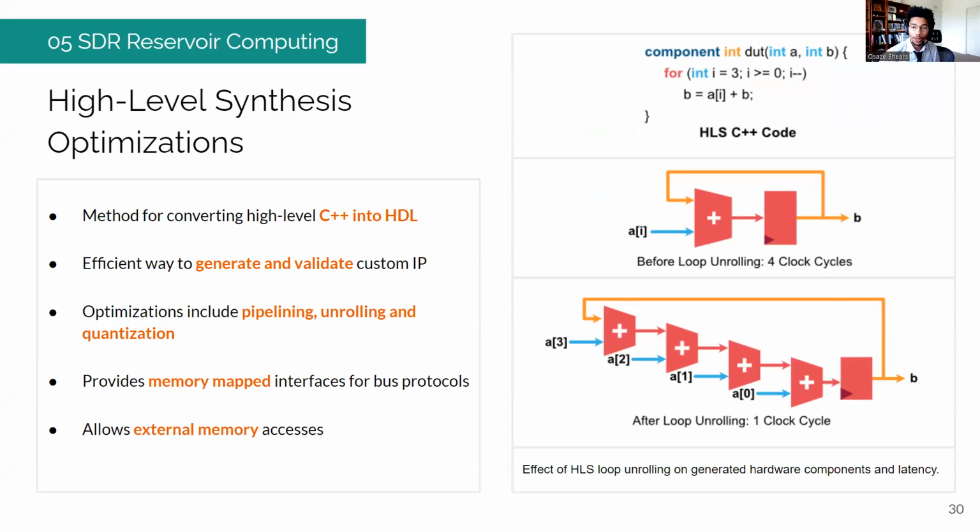Yeah, that's a pretty good question. I think the primary challenges were all related to just using the tool itself. So programming in C++, that's kind of a given, but learning about the different ways that the tool's optimization techniques can be used together to improve the design was one of the challenging things to figure out. For instance, you can execute the power function with different precision for floating point numbers in the high-level synthesis tool.